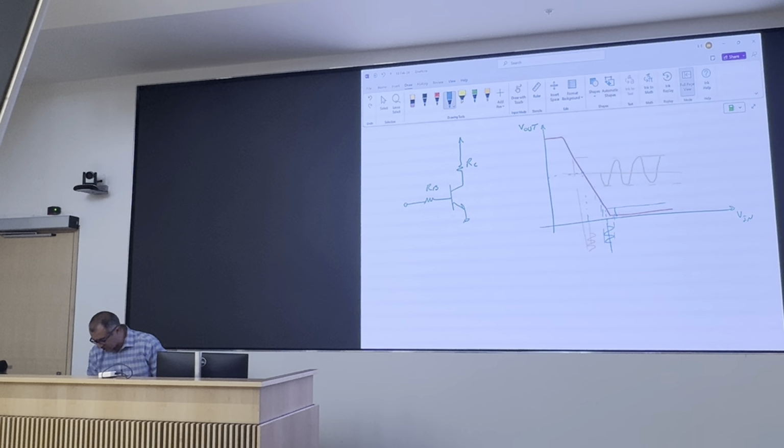hits the saturation limit, it actually is clipped, but then goes up and it's high. Goes down, hits the saturation, is clipped, goes up and it's high. So instead of having a nice sinusoidal waveform like the one at the top, you get distortion. The bottom of your waveform is clipped. You lose your gain, your device stops responding to your input.